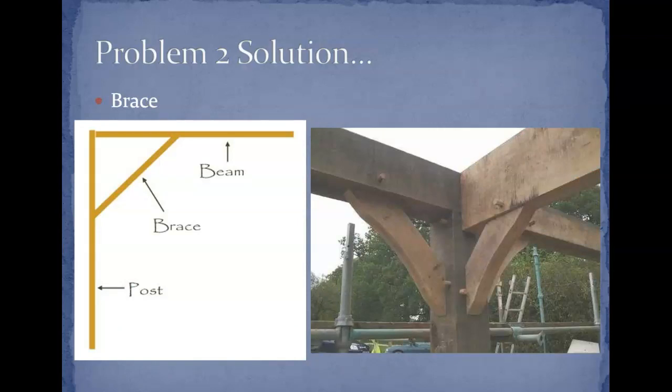Right, and here again we see the braces designed to hold some of the load as well as keep these joints in place from the beam to the post. We're keeping this in place with the brace, but this is also taking some of the load from the beam to the brace. Again, if you're just worried about the joint, a little L-shaped bracket there could also be useful. Depends on how much load you need.